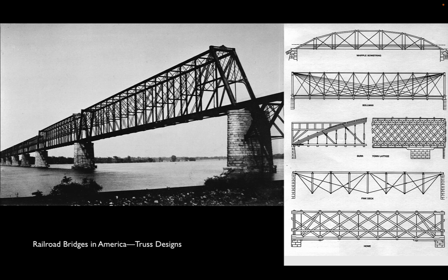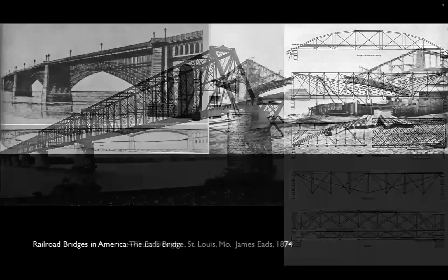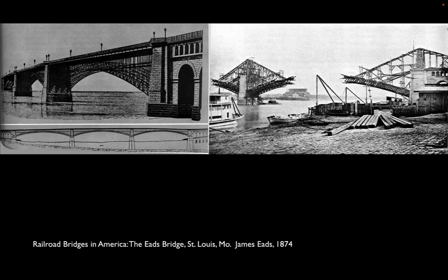If you think about it, that is analogous to the way that a beam works. All of these truss designs are basically designed to mimic the behavior of a beam, to put a compression element on top, a tension element on the bottom, and to fix the two pieces in shear so that they work together as a beam. Trusses can also get used, though, to make arches more efficient.